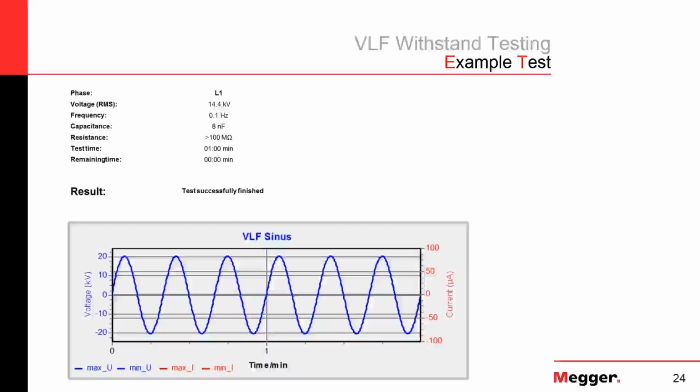So this would be an example of some test results from VLF testing. You can see on the picture there, it's just a constant sine wave over time. And in this case, the test successfully finished. The cable held the voltage for the time applied and did not break down. For this example test here, we only held it on for 1 minute, but IEEE does require 30 to 60 minutes. If we held it on for any longer, the voltage waveform on the bottom gets a little bit too squished to see.